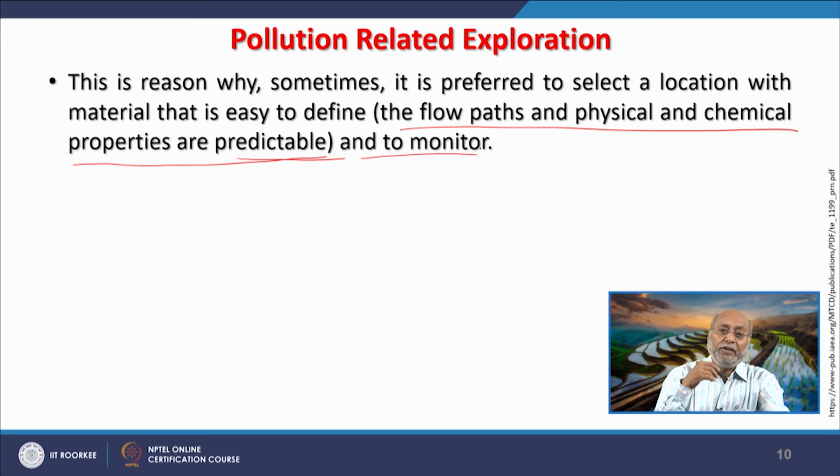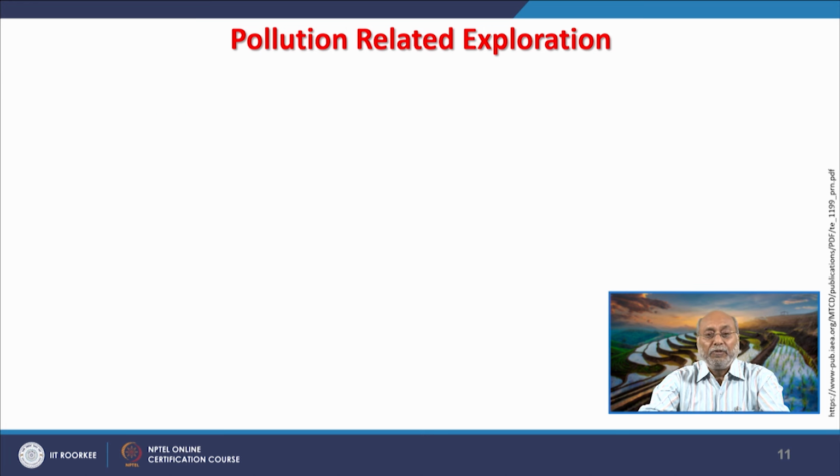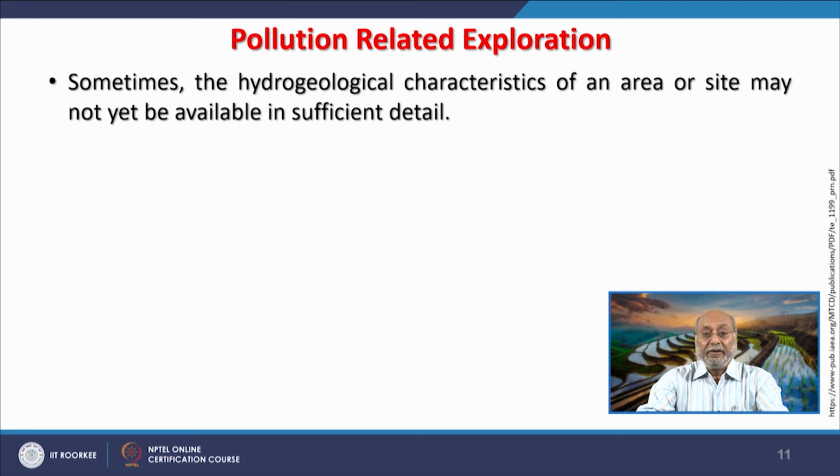Monitoring is also very important. You have chosen a site, you have started disposing, but how is it harming, whether it is really harming. As I have said, periodically the groundwater quality in the surrounding wells is assessed, and it is mandatory for any site developed for municipal waste or hazardous waste from industrial waste. All these sites are being monitored from the surroundings as well, and not only for water related things, but air related things also. So, air pollution, if a waste disposal site is causing it, is also being assessed nowadays. That has also become mandatory.